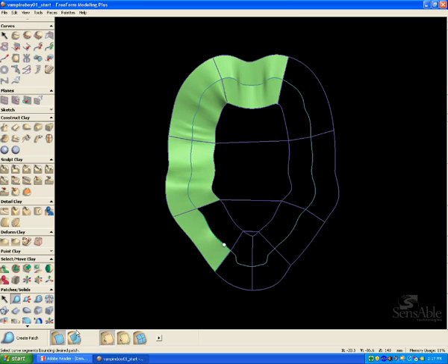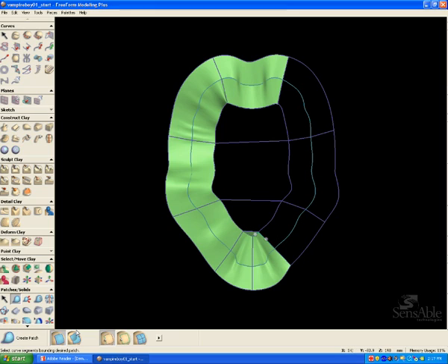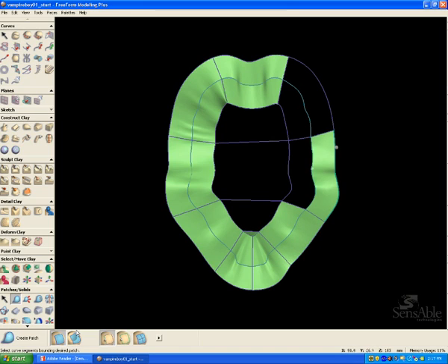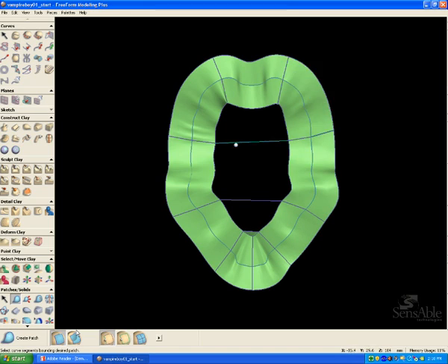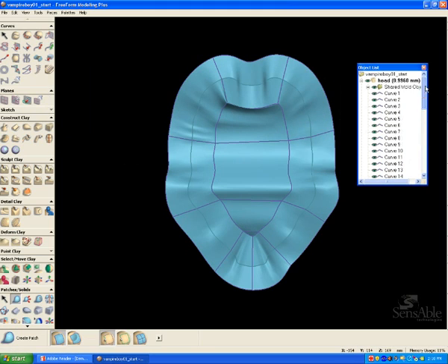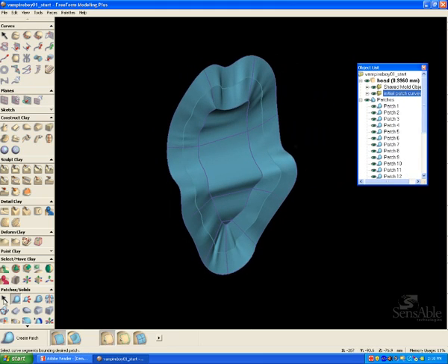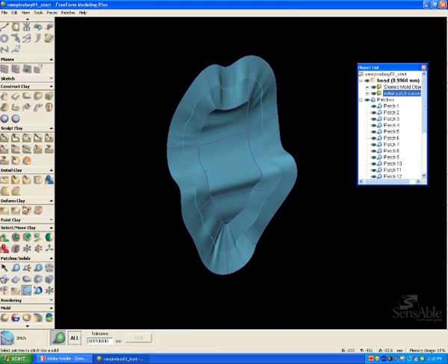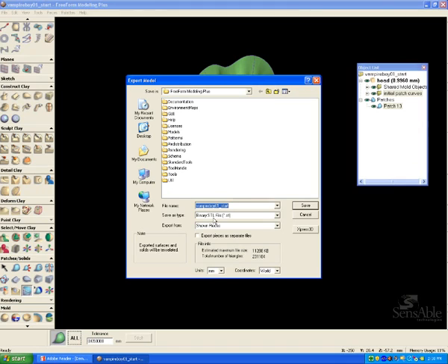So what I want to do is I want to use the original parting line as an intersection of the original part, but I want to create a mold box so I can create this complex parting surface. So I'm going to create this initial surface of several individual patches using the patch tools in FreeForm Modeling Plus, and I'm going to take all of these individual patches and stitch them together.